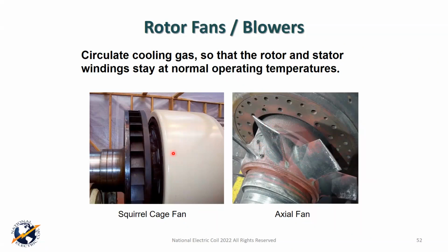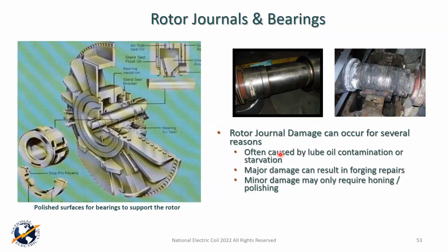Obviously, the purpose of the fan is to force cooling and to direct it. And there are different configurations. Some of them push, some of them pull. Getting them on in the right orientation is very important during maintenance. Most houses have pretty good procedures to keep that in check. And you need to do reasonable maintenance on these things over time, especially during major rewind and so on.